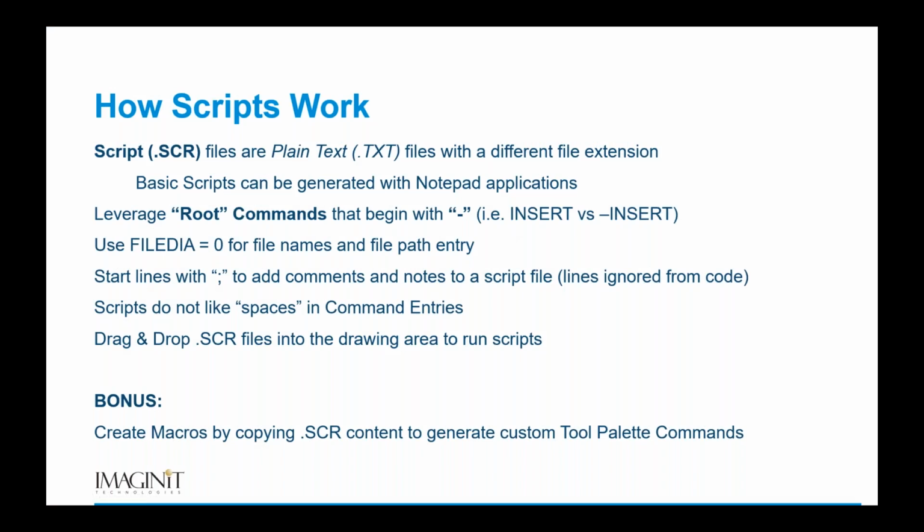So how scripts work, again, we're looking for that .scr file, and it's really just a plain text file that's got a different extension at the end of it. When we're looking for commands, we want to start out with root commands where possible to trigger the non-dialog box based entry. And then if you have to enter file names, this is another kind of tricky one with scripts. Script files do not like spaces in file names, because it's looking at a space as like an enter key. But if you do need to enter file names inside of a prompt, you can use FILEDIA.